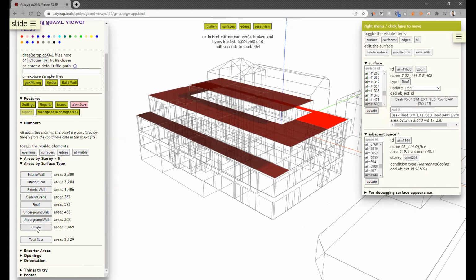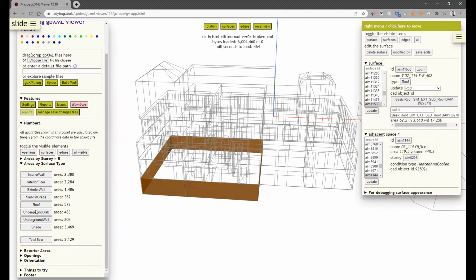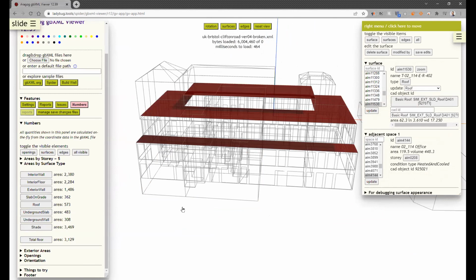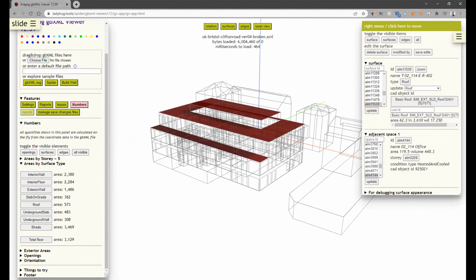are really, really helpful to check inside here. There's very minimal shading, underground walls, checking that your boundary conditions are correct so that when you import it, it comes in more seamlessly. So that's the last thing I wanted to share on the topic of gbXML.